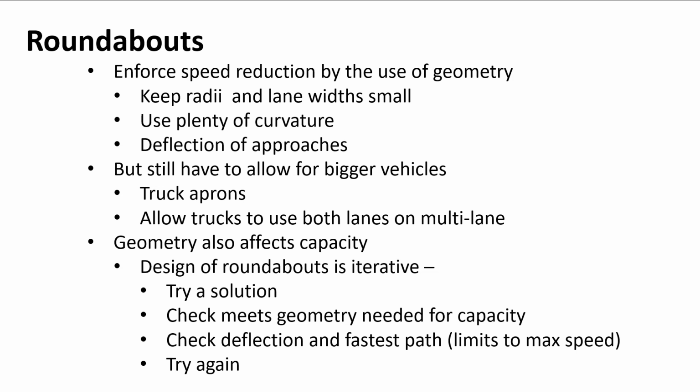So trucks are an issue, and for that we will build a special apron that the truck wheels can go up on, but we use a mountable curb, and then the truck wheels have this little paved center island piece in the middle that the trailer wheels in particular can ride up across. And so we make a very low curb, and we want it to be unpleasant so cars don't want to try to use it, but trucks are fine with it, and it's only about that 4-inch sloped curb, and it's pretty easy for a truck tire to come up across that. And we actually intend for trucks to use that.